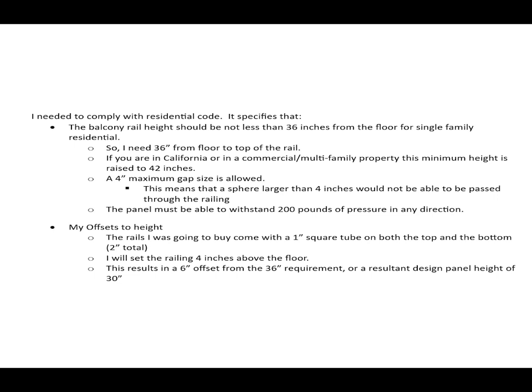A 4-inch maximum gap size is allowed. That means that a sphere larger than 4 inches would not be able to pass through the railing. The panel must be able to withstand 200 pounds of pressure in any direction.